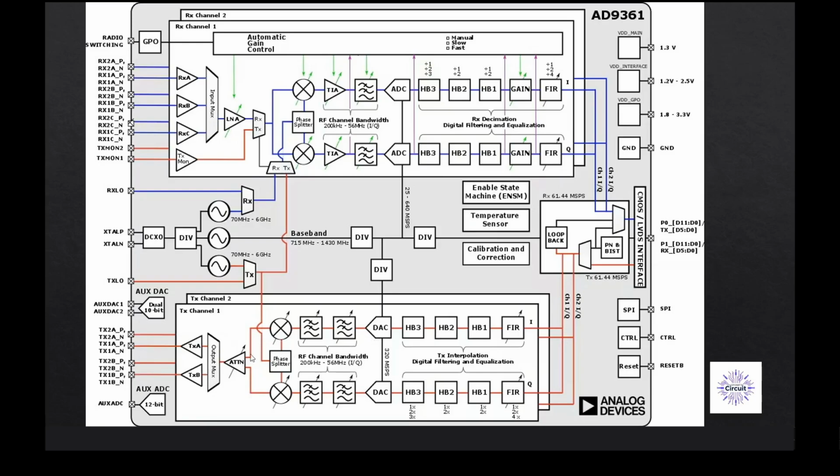So here we are just looking at one channel, but you can see that in AD9361 we have two TX channels, same behavior. So basically, if you want to generate baseband differences, we just change the phase relationship between channel 1 and channel 2 when we want to send the data to the DAC to create the signal.